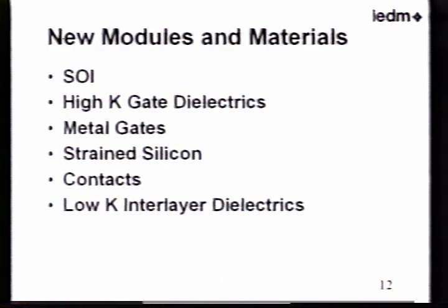We'll use low-K interlayer dielectrics, the layers between the aluminum or now mostly copper lines on the advanced logic devices. As we've got to higher and higher currents, smaller and smaller geometries and spaces between the metal lines, the traditional silicon dioxide and direct derivatives from silicon dioxide have been problematic for us and are creating issues. And so we will be altering that using low-K dielectrics in the back end. And then also just seeing improved conduction from those metal lines. We have seen more and more movement to the higher conduction copper interconnects from the aluminum. And I expect to see that and variations on the copper interconnect thing continue into the future.